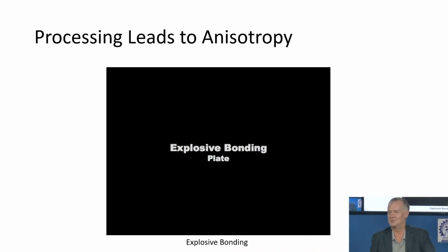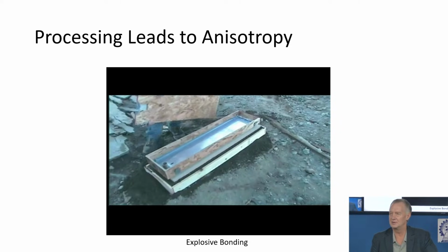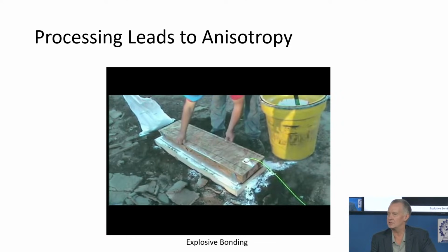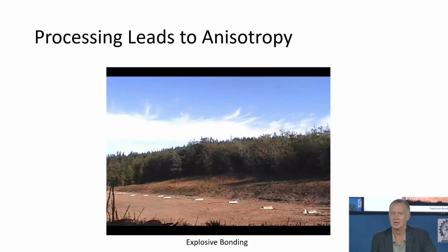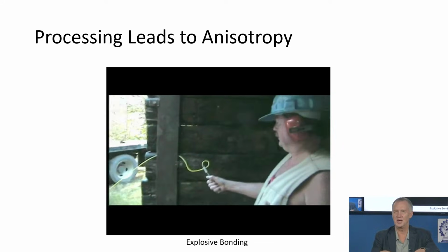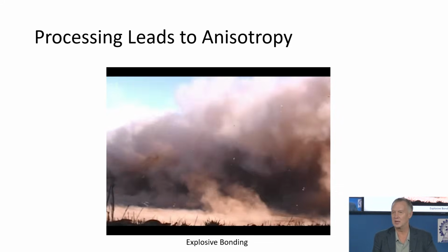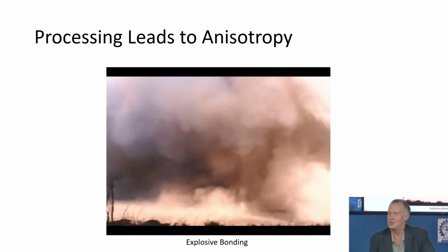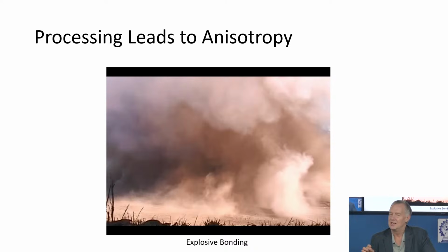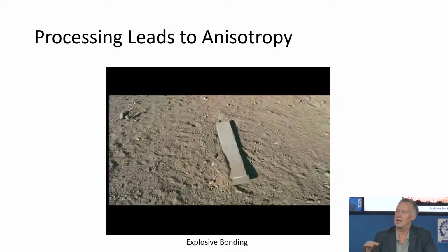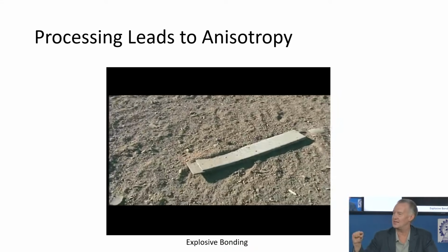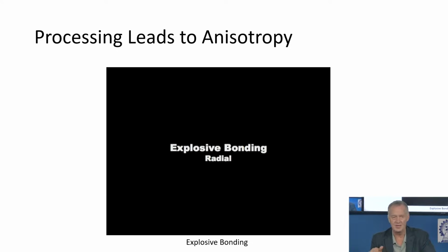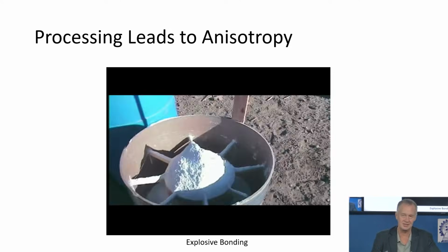I wasn't necessarily going to show this, but I like this video because in my state, there's a company called Pacific Aerospace and Electronics, and they do explosive bonding. So they get all these plates, put all the aluminum nitrate fuel oil, ANFO, on there, blow it up, and you have all these plates that join together. And I have a student who did his PhD in this, and so the texture that evolves along that interface is very dependent on how much ANFO charge there is and on what the spacing is between the plates before you slam them together. So you can control that very nicely, the texture that occurs at the interface, which is kind of interesting because it's just blowing stuff up, right?